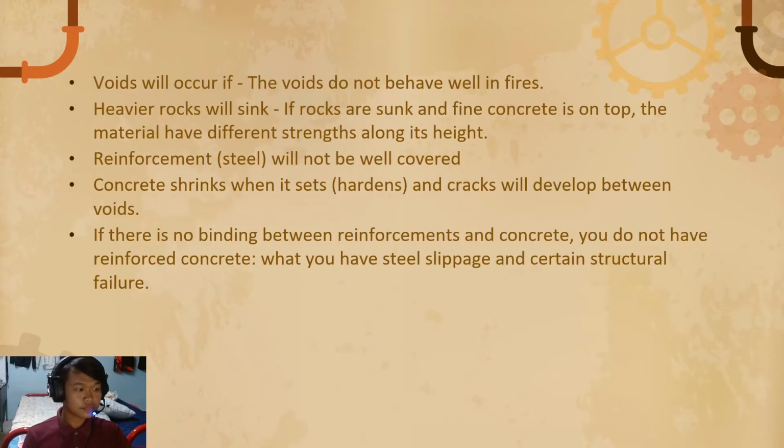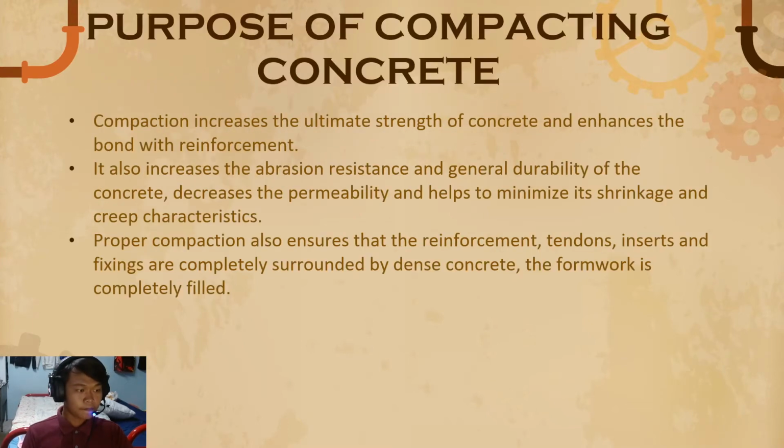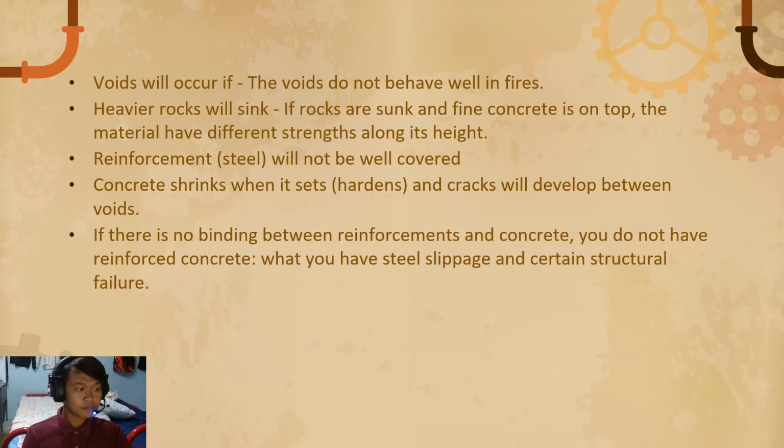Point 6, reinforcement still will not be well covered. Point 7, concrete shrinks when it sets and hardens, and cracks will develop between voids.